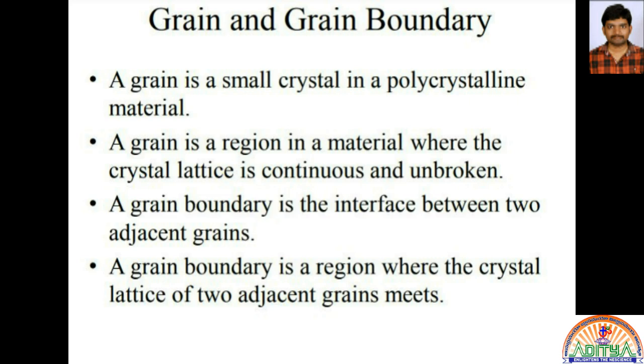So generally grains have a specific crystal structure and specific orientation, and some composition is also available for this grain. So these crystal structure, orientation and compositions are basic characteristics of the grain. Okay, for example, if you consider a piece of copper metal, each grain has a face centered cubic structure.